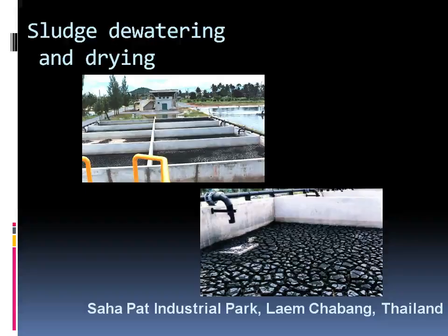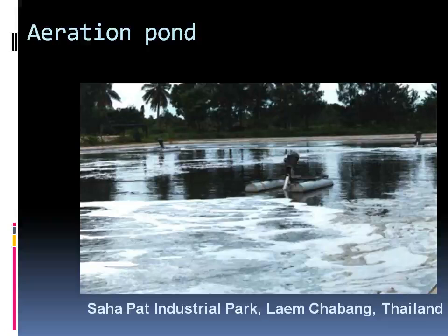Now, tertiary treatment in the case of a municipal sewage treatment plant. Tertiary treatment removes most of the chemicals that remain in water after secondary treatment. The major tertiary treatment methods include coagulation and sedimentation. Here the inorganic chemicals are precipitated by adding alum, lime, or iron salt.